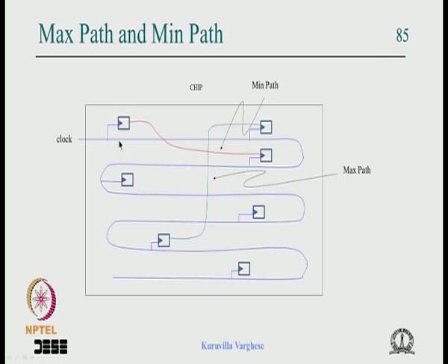Now this scheme does not even help if you insert a buffer here, a buffer here, and so on to offset the delays and the loading. That does not help because the buffer delays add to the skew. So you should have buffers which are balanced. In a simplistic way, you can put a buffer, then branch, another buffer and another branch, from the main route one more branch with a buffer, and so on.